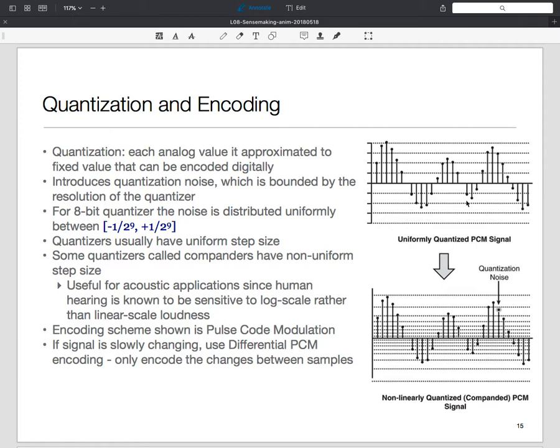Even though my signal may require only a sampling rate of 2 kilohertz, I can sample it at, let's say, 10 kilohertz and trade it off against lower bits. Those are the kinds of things that people who design A to D converters try to exploit.